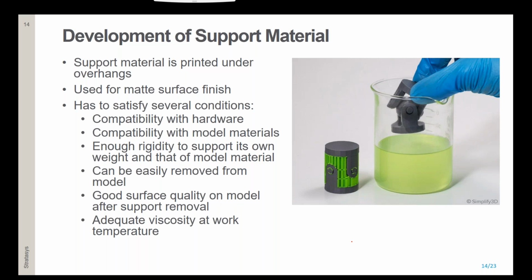And after we've done all of this, you would need to have good surface quality of the model, because if the model looks bad, nobody will print anything. And of course, it has to satisfy the viscosity for jetting, which for inkjet materials is very, very low.